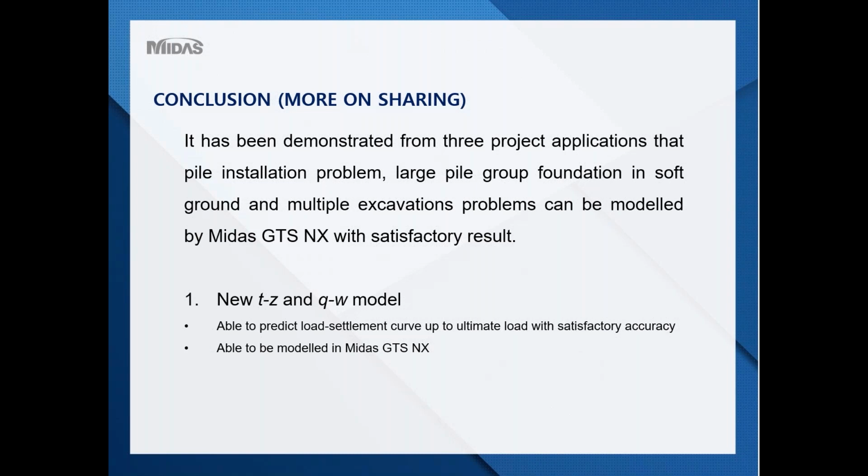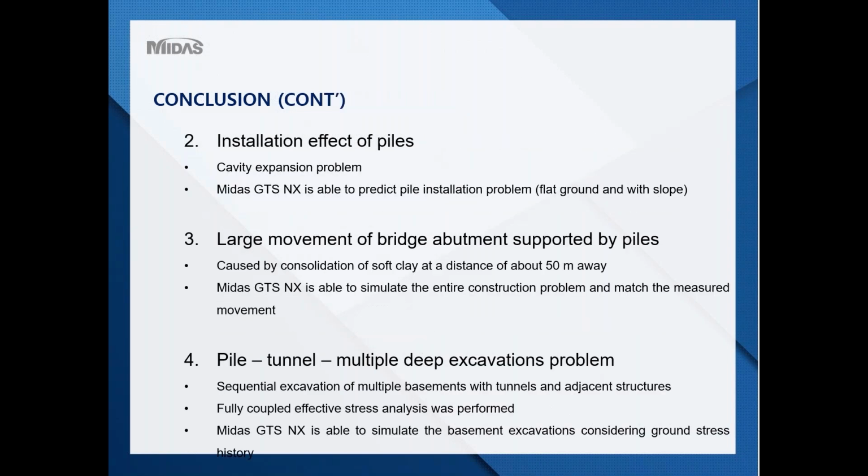I have introduced a new TZ and QW model, which can predict the load settlement curve up to ultimate load with high accuracy. And the point is, it can be implemented in MIDAS GTS NX. I have presented 3 examples of project applications using MIDAS GTS NX.